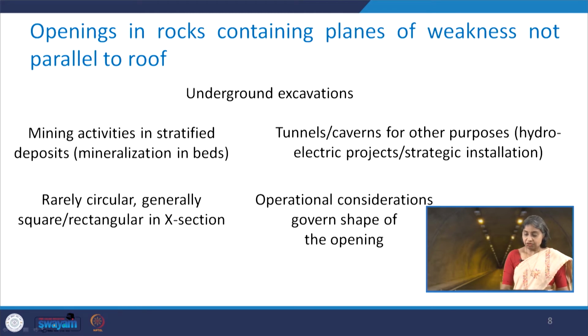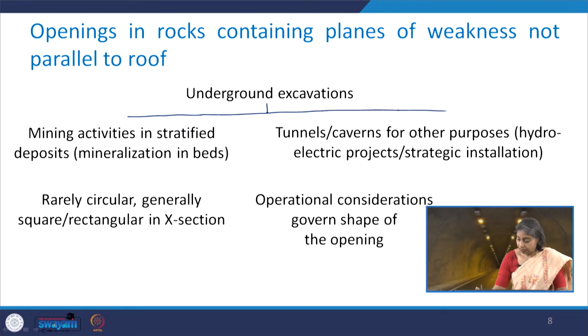Since the bond strength is across the direction, it will cause the failure because of the tensile in nature. Now coming to the openings which have the planes of weakness which are not parallel to roof. So we can have the underground excavation divided into two parts or two categories, I should say. The first one corresponds to the mining activities in stratified deposits.